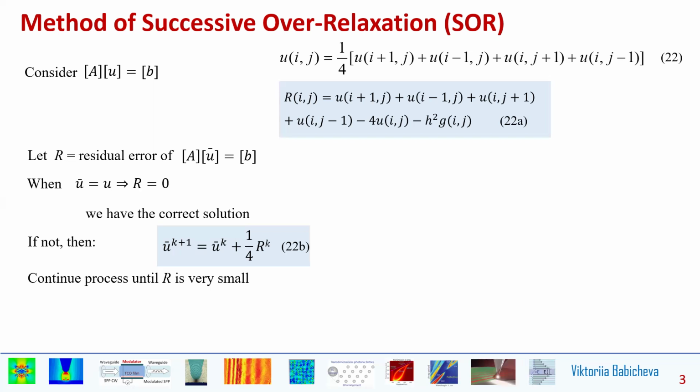Convergence to the correct value is approached as the correction term R^k tends to 0. The process of iterating repeatedly using the same equation for the nodal value is known as relaxation, from early structural applications in which the process was envisioned as relaxing stress.